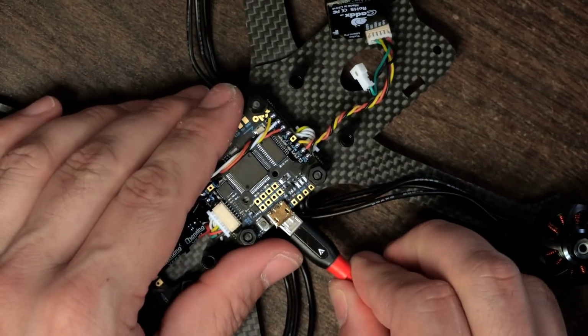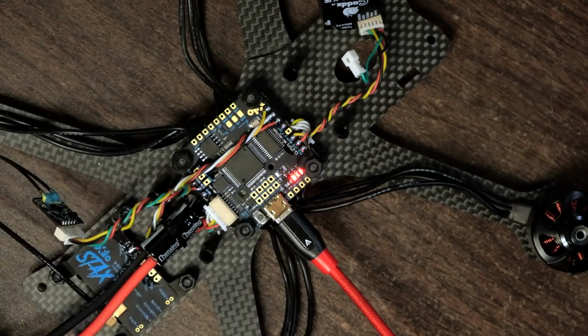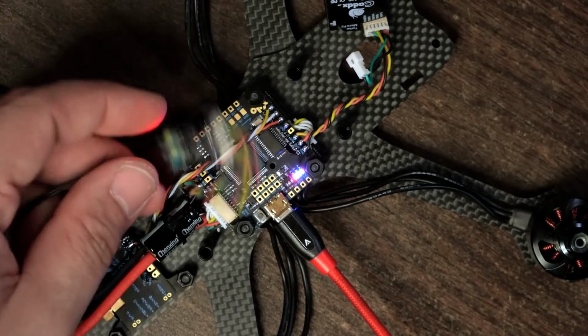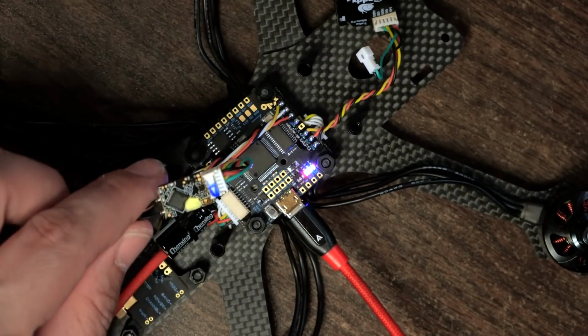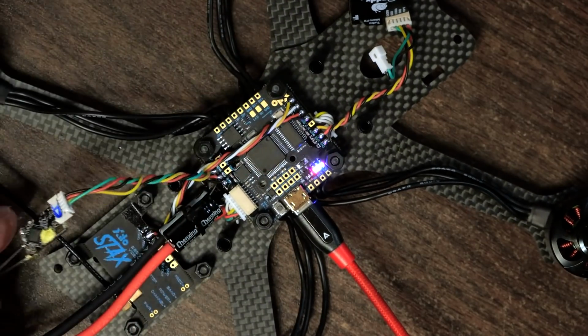Well, okay, now you're back and Betaflight and BLHeliSuite are installed on your computer. We're going to take a USB cable and we're going to plug it into the USB on the flight controller. When we do that, the flight controller will light up and you should also see your receiver light up. It's very convenient that this flight controller powers up the receiver when we plug in USB because it's going to make it easier to configure all this stuff.